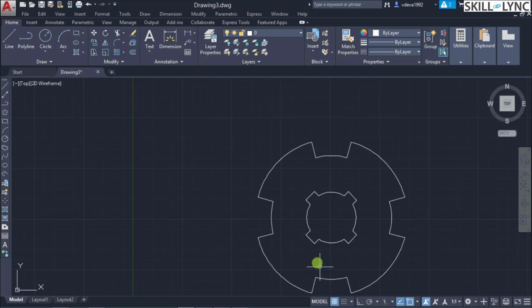This is how we can extensively use just the basic commands of move, offset, to ensure that we are getting the intended shape quickly. This array polar is a heavily reliable tool that you have to be very familiar with so that you can use it to your benefit. So next, let's draw the rivet holes.